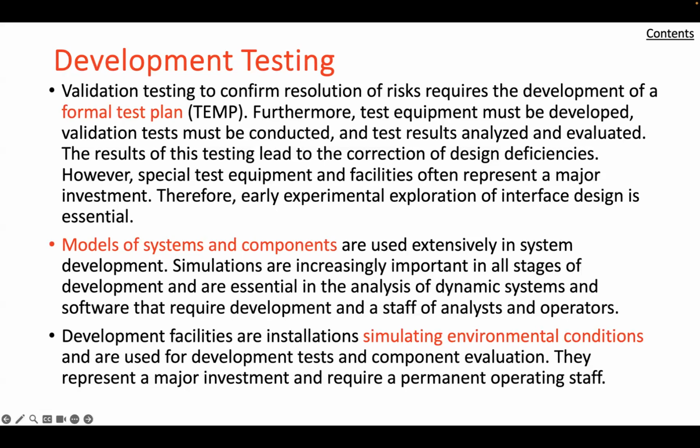For the test planning methodology, the overall testing approach must be designed to uncover potential design deficiencies and acquire sufficient testing data to identify sources of these deficiencies and provide a sound basis for their elimination. This is very different from the approach that presupposes success and performs a minimal test with scanty data acquisition. Whereas the latter costs less initially, its inadequacies often cause design faults to be overlooked that later result in program interruptions, delays, and far greater ultimate cost.